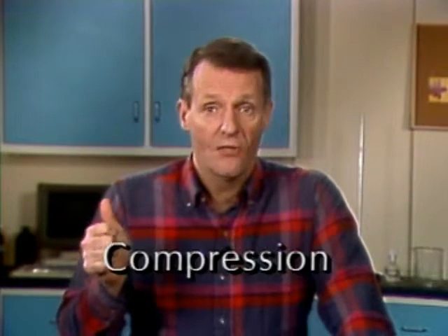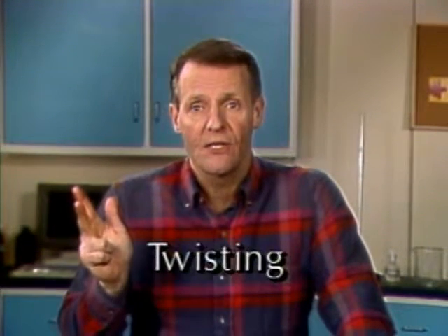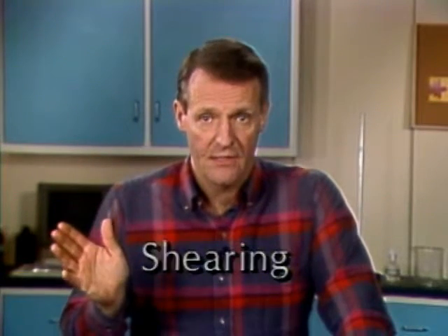A condition relating to solids is stress. Stress is the result of applied forces. These forces can alter the molecular structure of a solid, causing it to change shape. There are basically 5 types of stress that can affect solids: tension, compression, bending, twisting, and shearing. In a way, tension and compression are opposites. Tension occurs when external forces try to pull a body apart. And compression occurs when external forces push on a body. That is, try to push the particles of a body together.